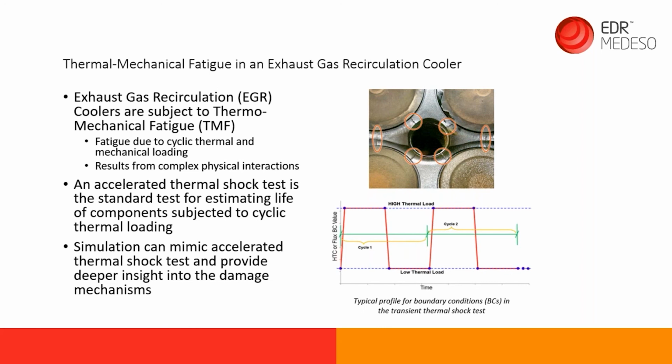So in this case, this is an engine component which reduces emissions by reducing in-cylinder temperatures. Now, these devices are subject to thermal mechanical fatigue, as is common with a lot of devices where you're conducting CHT. So what we've got to do is run a CFD analysis to get a heat transfer coefficient and then pass that on to mechanical.